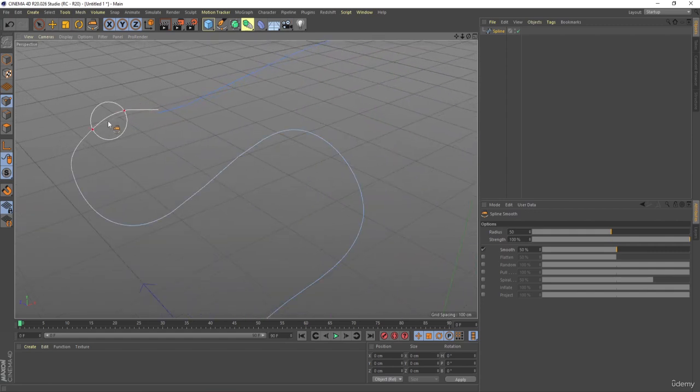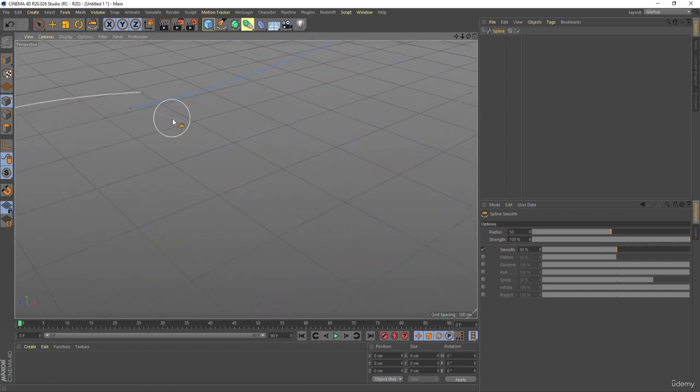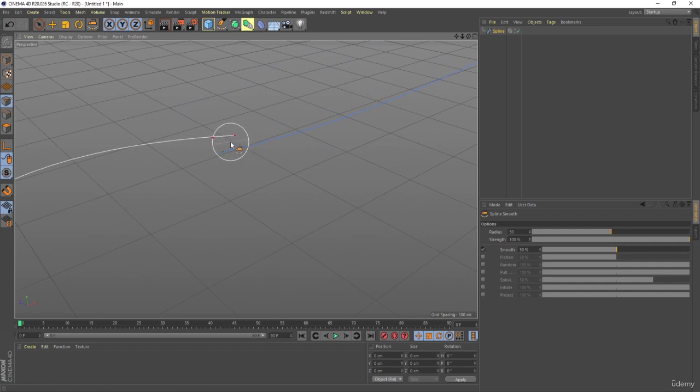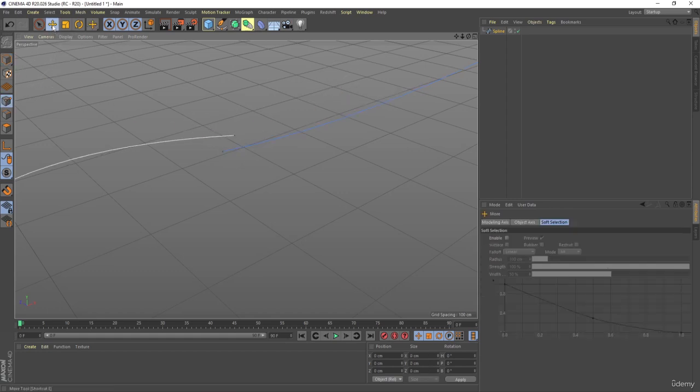But one thing about this tool is that, if you see properly, because this is the sketch tool, it's really difficult to close these points. So what will we do if we need to close that? For that, we will select our point view, and we will select our move tool. I'll select this point first, and by holding shift I'll select this point.